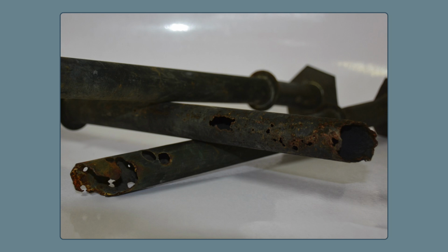This one shows the failure, so the metal dusting at the front end of the tubes that causes pitting. But you can see a layer where, say, the middle tube, it's a little bit gray-white, and then it transfers to black. So if you move towards the back end, the temperature wasn't in the range for metal dusting to occur. So only the front section and a part that has obviously corroded off was within that temperature range. So that's quite distinct with metal dusting, that it is only susceptible in specific temperature locations.